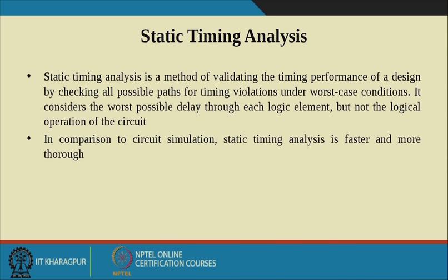In comparison to circuit simulation, static timing analysis is faster and more thorough. Simulation has different aspects: we can do functional simulation, logical simulation, and circuit simulation. But here we are doing timing analysis, only calculating the timing information of each of the nets and each of the gates, under the worst case condition. We are not considering the best case condition here.